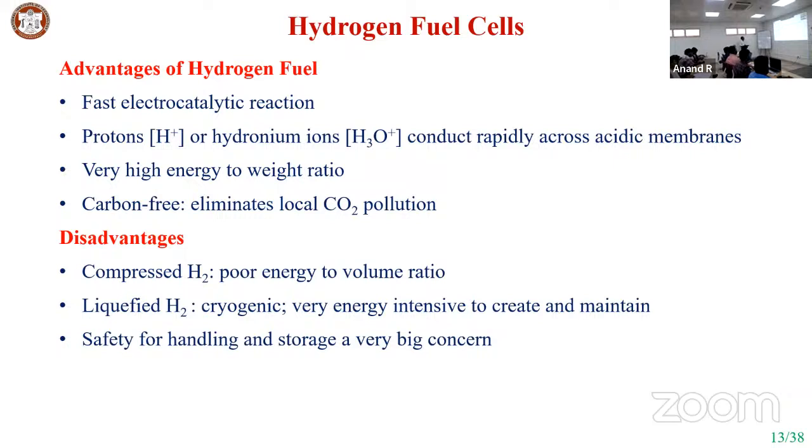So this is also an energy intensive process. And there is the safety of handling, because hydrogen is not going to create any pungent smell like ammonia. So you cannot ensure whether hydrogen leakage is happening or not. So you need a hydrogen detector. Also, the laminar flame velocity is very high, so when a fire occurs, it's very difficult to control the flame. So safety in handling hydrogen in the desired application is going to be a challenging task, because you cannot identify whether the leakage is happening.